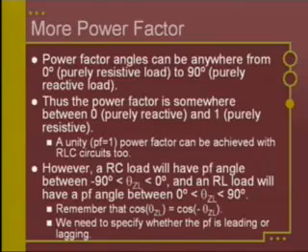And so one of the final things that we can do is, because those capacitive loads will have negative phase angles and the inductive loads will have positive phase angles, we have to differentiate whether the power factor is leading or lagging. And normally what we're going to see is it's going to primarily be an inductive load, because industrial loads tend to be inductive. When you get into your motors class, you're going to see AC motors, DC motors, heavily inductive looking loads, and those are going to create primarily lagging power factors, and so we're going to want to try to correct those back up.